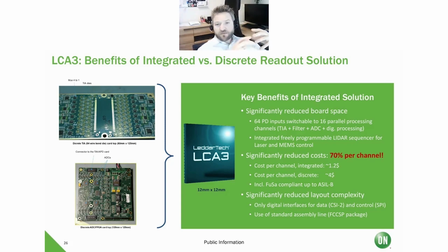Processing channels complete means we have integrated for all 16 channels the transimpedance amplifiers, then necessary analog filters, plus the ADCs for all 16 channels, and then also some post-processing. But this is not everything. We also have integrated, and this is a huge advantage for a LiDAR solution, a freely programmable LiDAR sequencer, which is able to control not only the lasers, but also to be controlled with the MEMS mirror solution. So it's not only the capturing unit, there's also sequencing included.